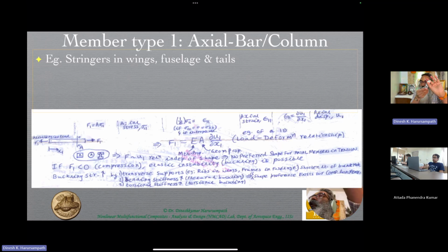On the other hand, the bottom portion is typically under tension. This is essentially because of the conventional lift distribution that we have, with upwards bending, so the tip goes upwards, which means that the bottom stringers are all under tension. So both of those are included in this particular slide. Similarly, in the fuselage also you have stringers running through the length that you see over here.